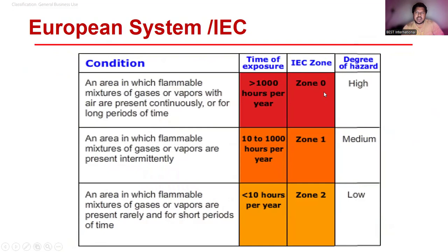So always in zone 0, any repair, maintenance or any sort of project you have, including inspection even, or changing some parts whatsoever, you have to be very careful how you're going to do it. Like in Aramco we have equipment opening and line break. Same way, what isolation or LOTO permit system you have, how you're going to isolate energies, how you're going to lock and tag, how you're going to validate, how you're going to purge by using nitrogen, how you're going to make sure LEL is 0% if it is hot work, and especially in zone 0, how you're going to make sure not a single chance of ignition is there, which can destroy the whole process. And you can't issue the permit, by the way, until you have successful isolation and LOTO application implemented. You can't even sign the permit.